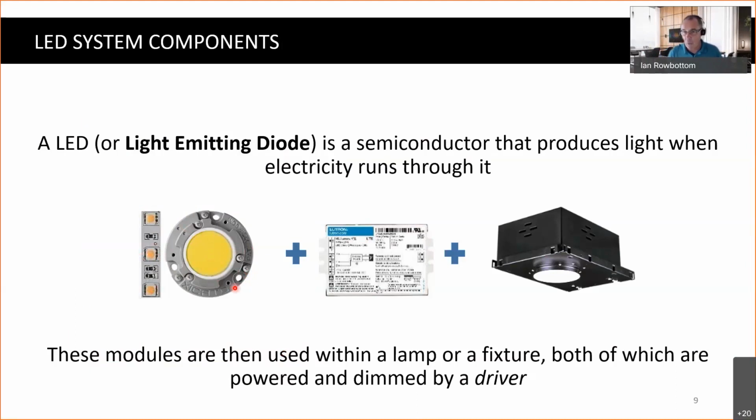And why is it not white? Well, the color is the phosphor coating. Typically, an LED that we use for white light is blue. Well, we don't like blue light. So what we do is we use a phosphor coating in front of the LED, and that converts the blue color to shades of white. The phosphor determines the color temperature of the static white LED.